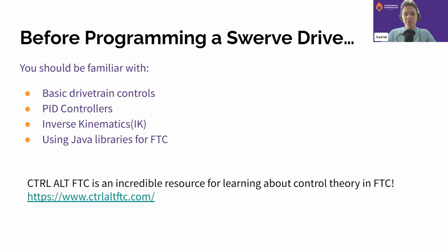Additionally, you should be familiar with what a PID controller is. If you don't know, it's essentially a math equation that allows you to determine how much power you need to get a system from one point to another. A good way to use this is for an arm, or in our case, the angle of the swerve pod.